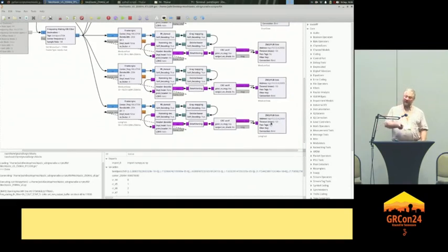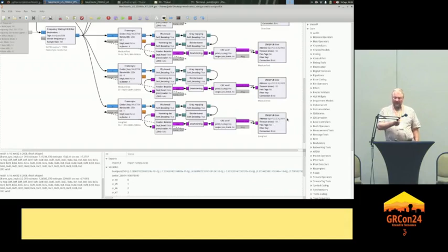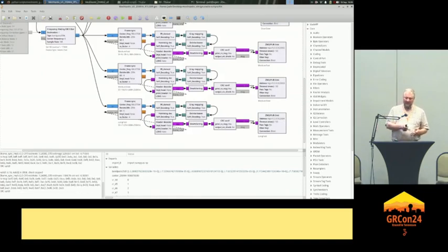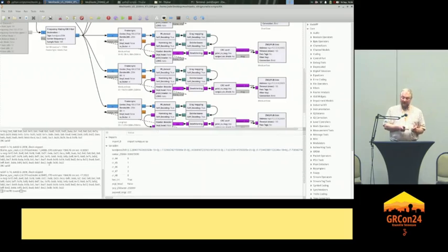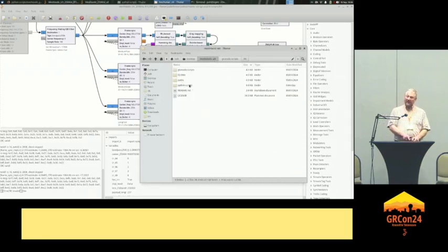Along with this, I'm using 0MQ, and we have the ports 20,000 through 20,004, each of their own ZMQ, so we know which port goes to which preset. From here, you see in the bottom corner there that we're seeing LoRa data right now. We're decoding it directly. And we now have to have another accompanying program in order to decode that data further,